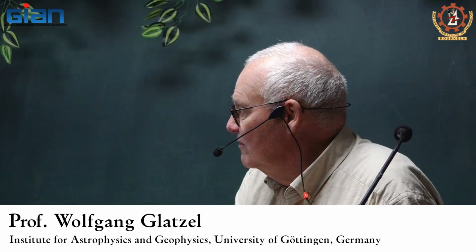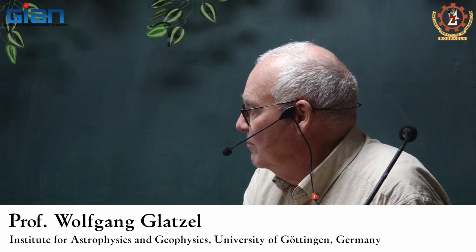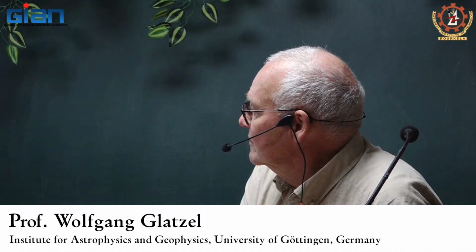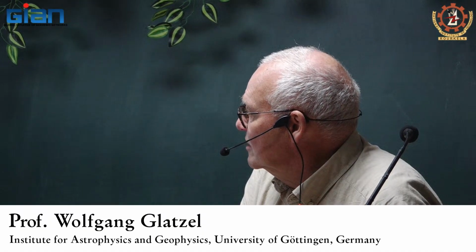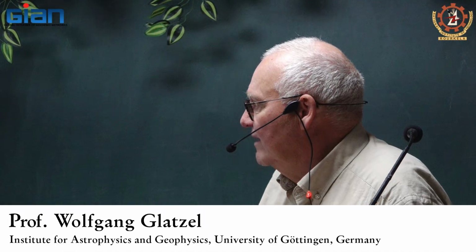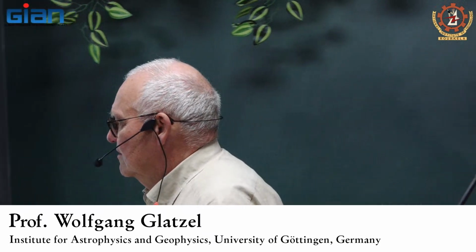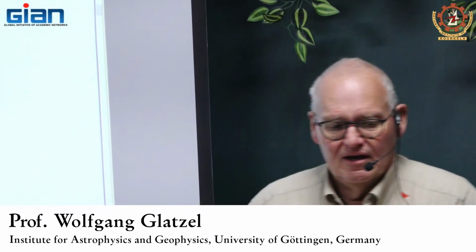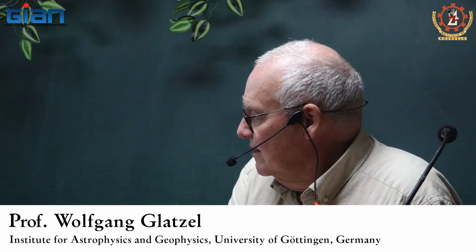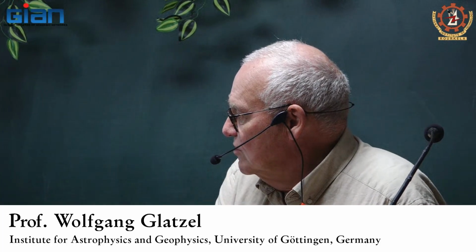We started then with the mass conservation, and we arrived at the equivalent of the mass conservation, which is the continuity equation, either in the Eulerian formulation or in the Lagrangian formulation. The next law of conservation was the law of conservation of momentum.